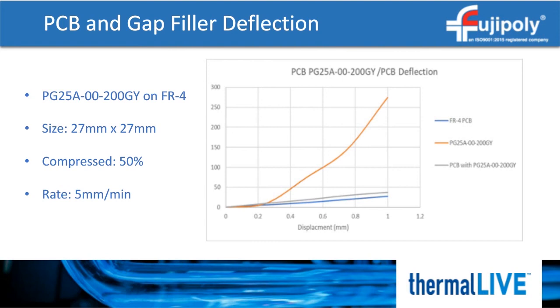If you know the relaxation loads for the pad, you can match it up to the PCB and get the actual final resting point for the PCB. For example, if you know the pad after 24 hours will go from 150 to 50 newtons, you can figure out just where the PCB will finally rest.